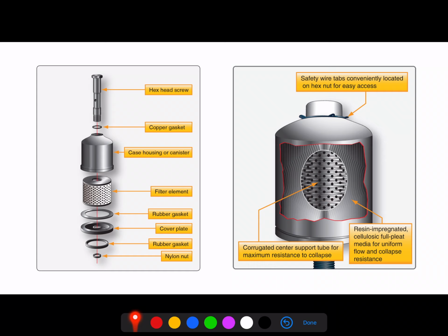Its distant cousin over here is the cartridge style filter, where we have a separate filter element that can be replaced and the remaining housing is actually a part of the engine. Fundamentally, both of these filters are going to operate in the same fashion, just the spin-on filter is a little more convenient, and in a lot of cases the filtering elements are a little more robust than we may see with the other style filters.